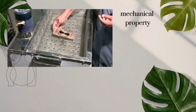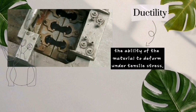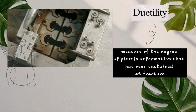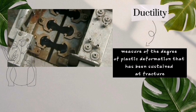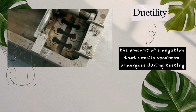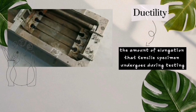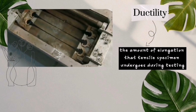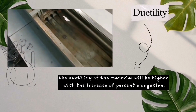Another significant mechanical property is ductility, which in general is the ability of the material to deform under tensile stress. Precisely, ductility is a measure of the degree of plastic deformation that has been sustained at fracture. Ductility also means the amount of elongation that a tensile specimen undergoes during testing. The ductility of the material will be higher with an increase in percent elongation.